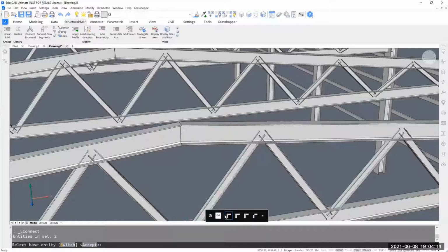It's a little confusing because I can't use my mouse to click on those, but I can use either my control key, or if we read at our command line, we can click switch or type S. So when I do that, any one of those three, you'll see my graphics change to go through these different connections. So is the L connection, the miter connection, things like that. We actually want that first, that mitered connection is what we want, so we can go ahead and accept that.